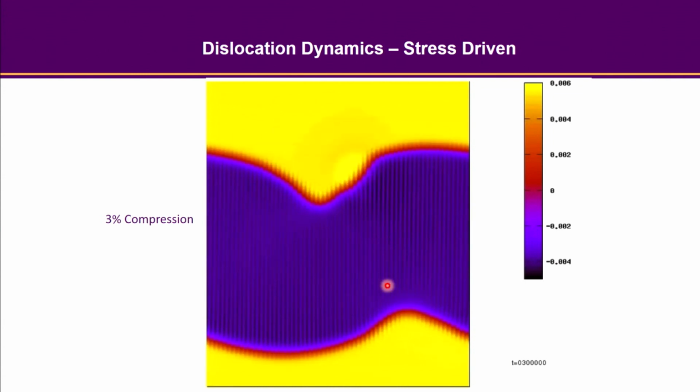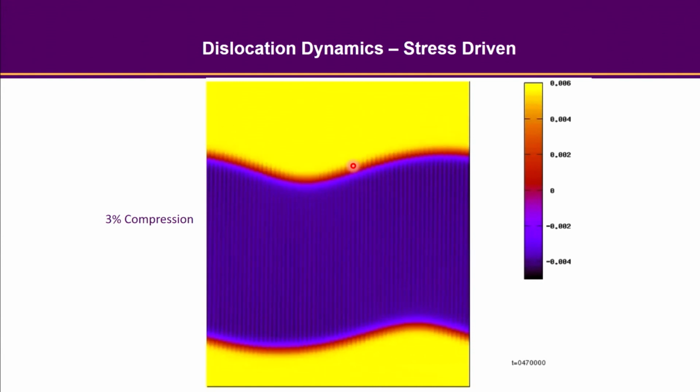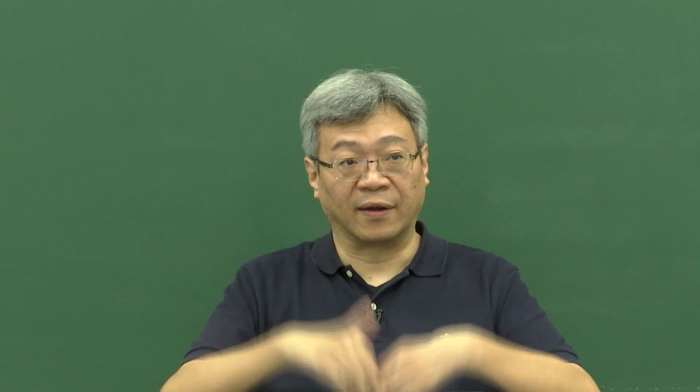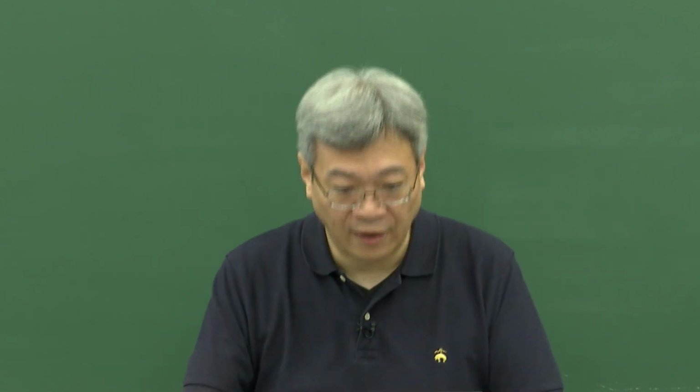As we just described, as the dislocation passes by, it effectively removes one of the extra planes. If there's more time for this dislocation to propagate to the other side, then maybe you are expecting a dislocation forming here. Depending on the sign of the Burgers vector, they might come together, combine and get annihilated. So that's actually the next simulation.